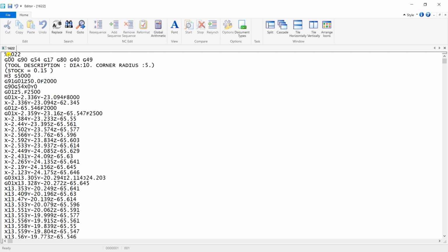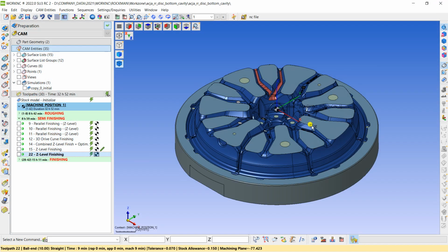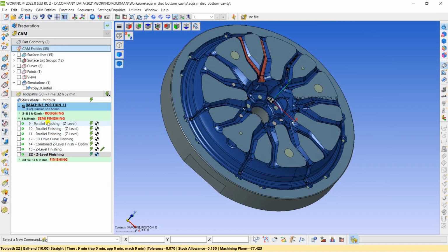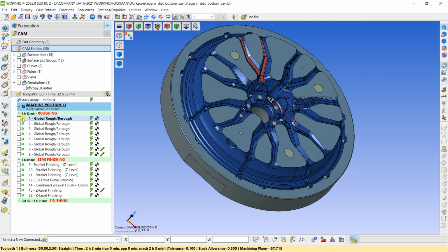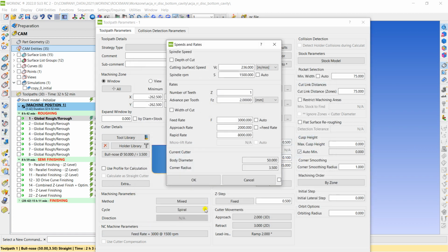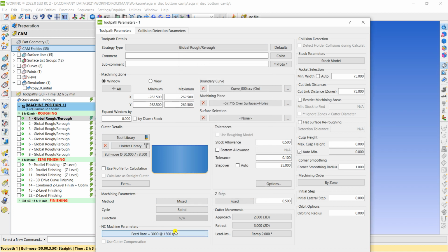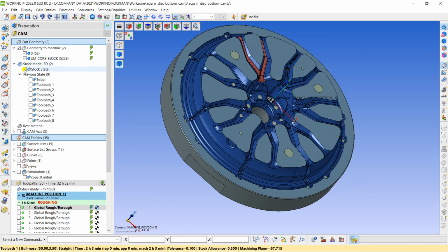In manual programming we have to write all these codes manually, but our CAM system will generate them automatically. We only have to define the toolpaths and the tooling strategies, like our RPM, the tool, the method, like is it down milling or up milling, or feed, RPM, stock allowance, tolerance, step over, depth of cut, is it running at a ramp angle or vertical, areas to ignore.